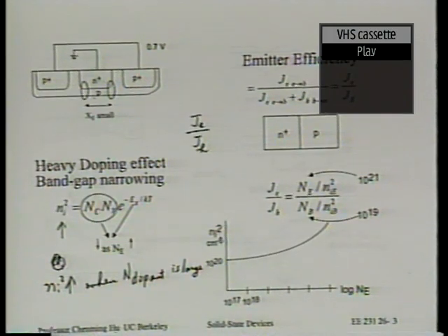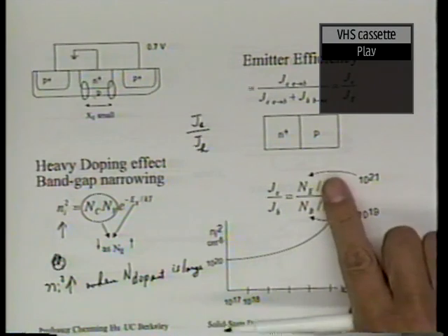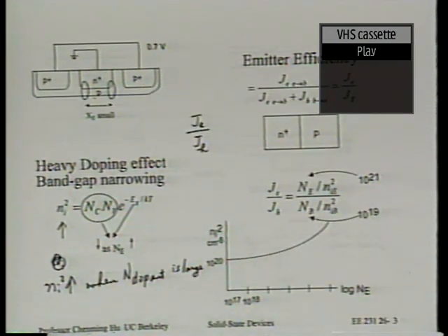I will not go through the derivation with you. If you look at the derivation of the p-n junction theory, you will find this is it. We usually omit this because they are often assumed to be equal. But if they are not equal, we'll have that term. Now, the trend, unfortunately, is that when the doping concentration is large, NIE increases like this, roughly speaking. Starting at 10 to the 18th, we'll start to see this rise. And below 10 to the 18th, it's pretty much constant. We don't have to worry about that.